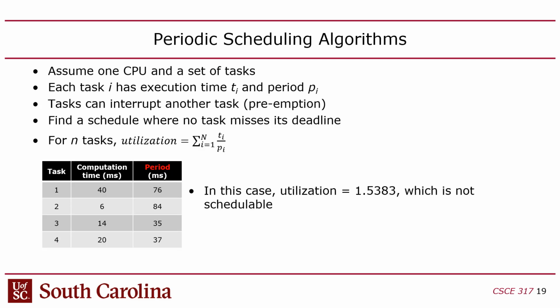The more common situation is to have a periodic scheduling algorithm, which is where the deadline of each task is also its period. It's the amount of time between reissues, right? So whenever a task finishes, it goes to sleep until the beginning of the next execution period, in which case it becomes awake, and then it's either going to be in the running state or the waiting state, right? Until it gets executed, at which point it goes to sleep again. So that's the period. This is what you have to use if you use any kind of a discrete control system, a periodic scheduler.